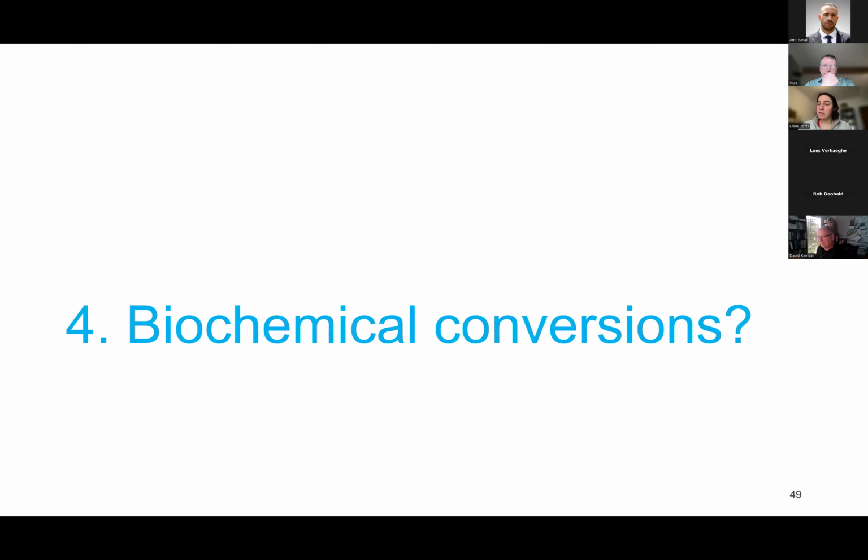Two last slides. Of course, we just talked about solids and settling. If you have a decent sludge blanket, you might have quite a lot of mass in the settler. So will there not happen any reactions? Will there not be any bioconversion? There might. For instance, denitrification in the settler is an aspect that might occur.